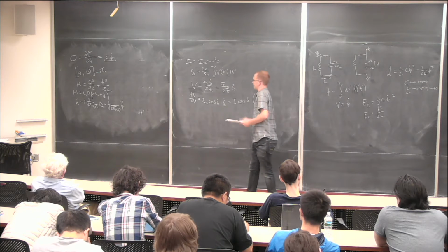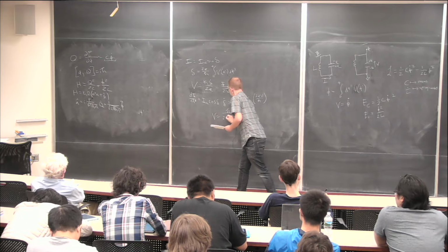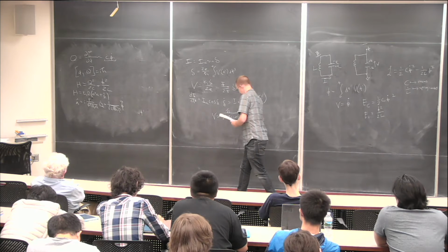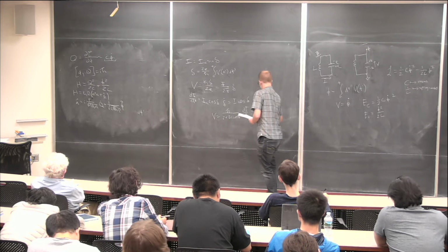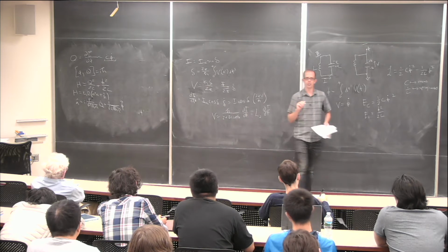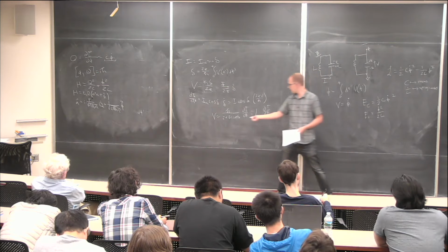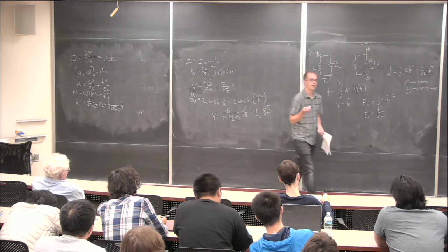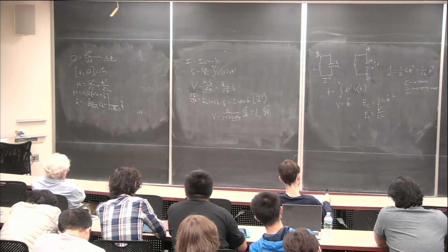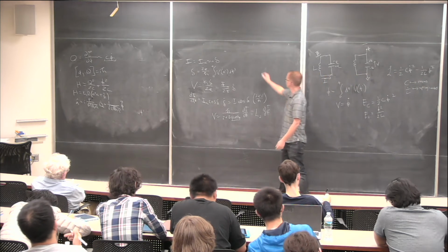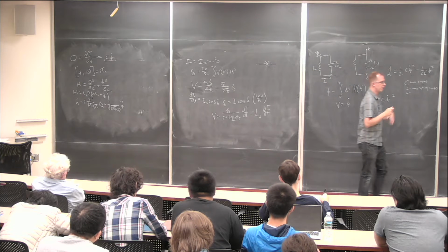That says that the voltage is equal to h bar over 2e I_C cosine of the phase difference, times dI/dt, which you can call L_J dI/dt. So this looks very much like an inductor, right? It has a voltage which depends on the derivative of the current, except the value of the inductance has a cosine of the phase difference in it, which means the inductance is essentially a nonlinear function of the current. So the Josephson junction, which we draw as an X in circuit world, is really very much like an inductor, but a nonlinear inductor.